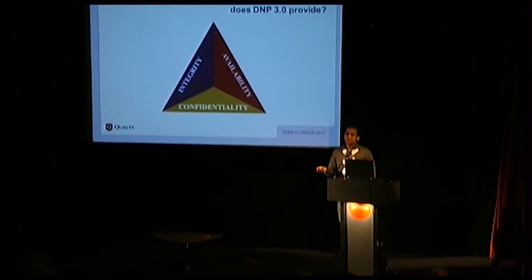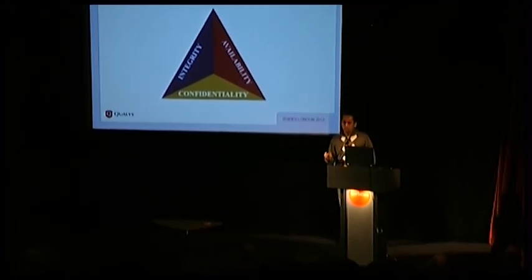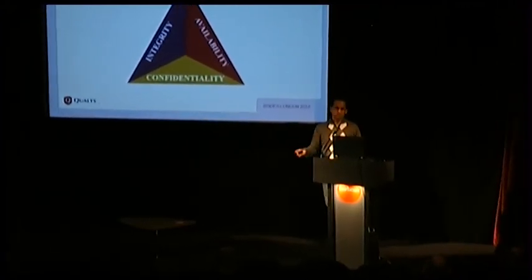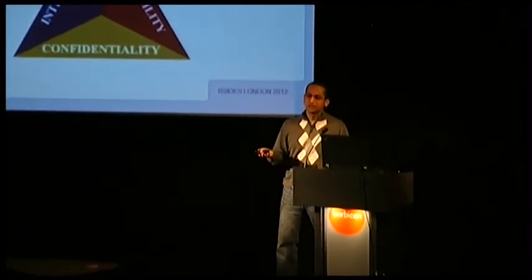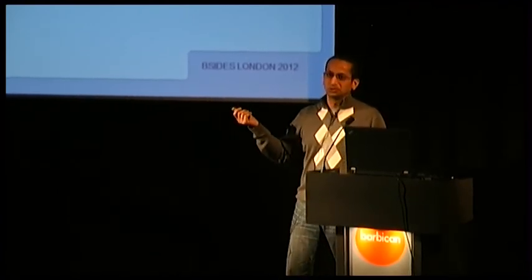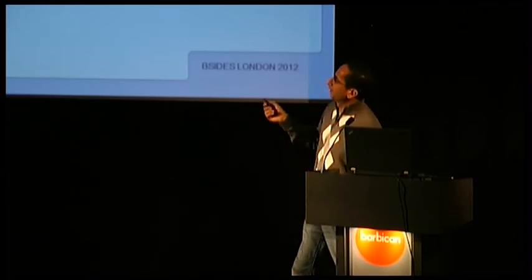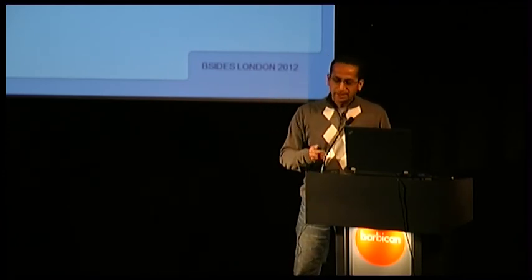So we again did the same thing. If we found DNP3 in our customer's environment, our signature said, okay, you are running DNP3, and this is the screenshot from the open source tool. It basically scans, trying to find if DNP3 is running. And if it does, then it says, okay, it's not a very secure protocol, so try to have your security in some other form around this protocol.